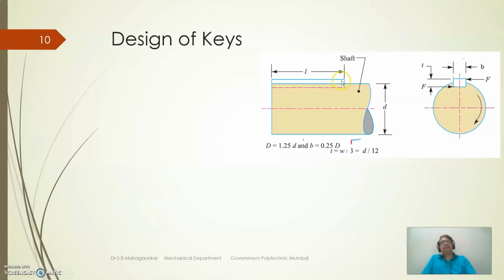And the other one, as the key is a different material and fits in the recess of the shaft or recess in the hub, as you see here, contact stresses are developed between the shaft and the key, or between the key and the hub. So the key is mainly designed for shear failure or for crushing failure.